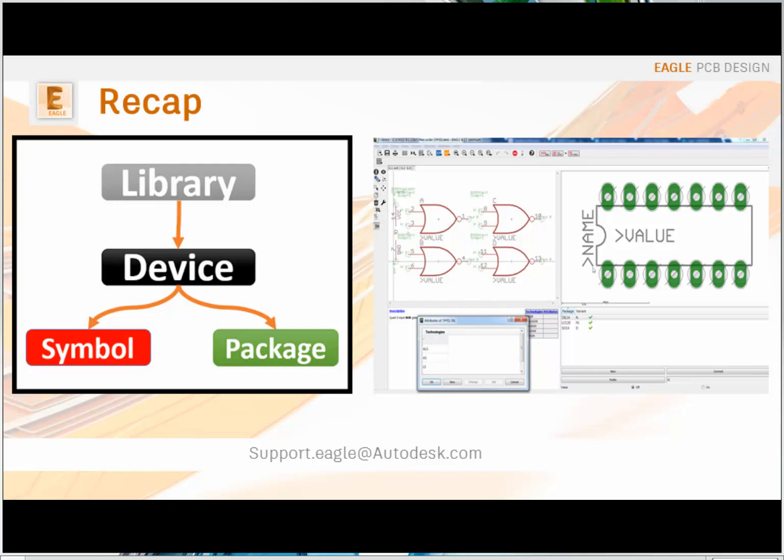On the package level, please remember, it's paramount that you're using the appropriate grid. So always find a common denominator grid that will satisfy the placement of your pads. It is so important that you use the appropriate grid. Once you have your package and your symbols created, go ahead and move on to the device, where you're going to bring in your package, bring in your symbol, assign which pins go to which pad, and provide some sort of a prefix that makes sense to you or logic to the component.